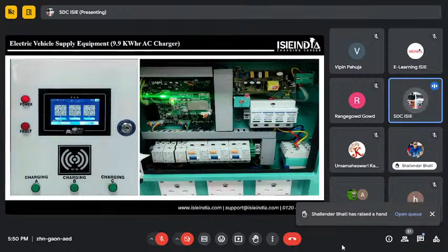I'm not explaining the complete circuit, but I'm guiding you on the essential components inside the charging infrastructure. First we get a power supply from the back-end input power supply, from an outer three-phase connection, with earthing wire and neutral wire, and three-phase MCBs, right? After that there are voltage distributor connections, and then an auto restart connection.